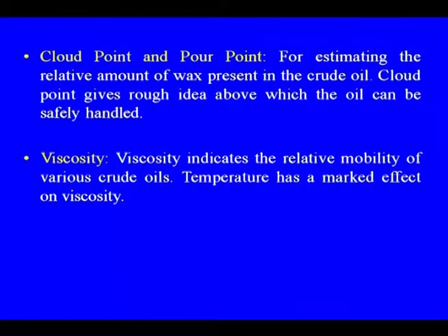One of the problems you see is in the case of wax, and even in the case of oil also, it gets solidified during the winter season. Viscosity indicates the relative mobility of the various crudes. Temperature has a marked effect on the viscosity, because in many places where they are using fuel oil, they face trouble during the winter season because of the low temperature.